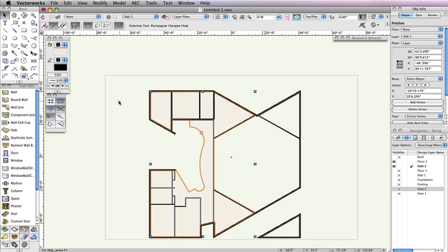As you can see, this is only a portion of the remaining slab. So again, enable the Polygon tool in the Basic Tool palette, and follow the vertex points set in this video, and set these same points in your file. Just like last time, don't forget to double-click to complete the polygon.